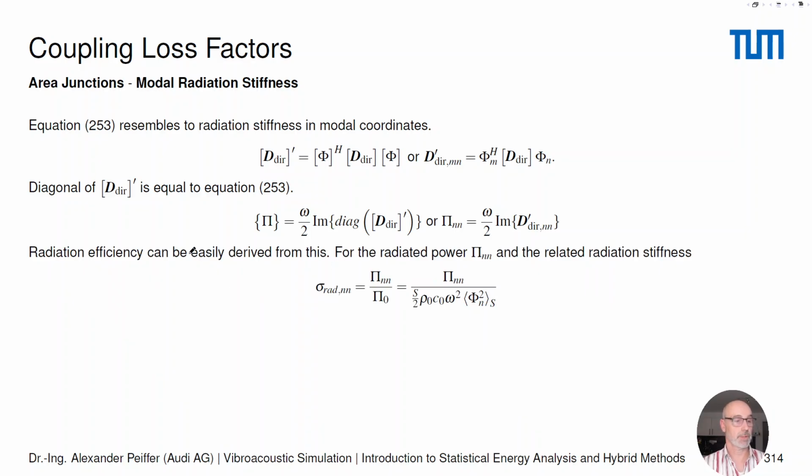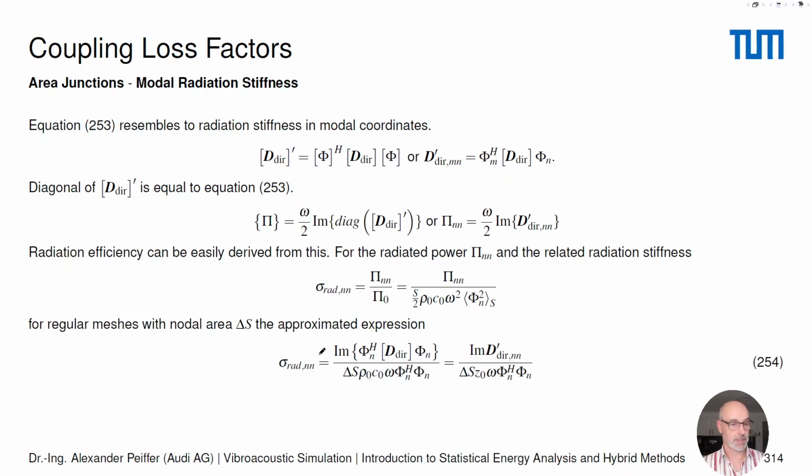And also very important, just remember we had this funny formulation of the so-called radiation efficiency, which relates the radiated power of a vibrating structure to the radiated power of a plane wave of the same velocity or displacement. And then we would get this expression here. So this is given by a clear formula. And this is just the surface average, because the radiation efficiency is using an average velocity over a plate. And this gives us another approximated expression for the radiation efficiency.